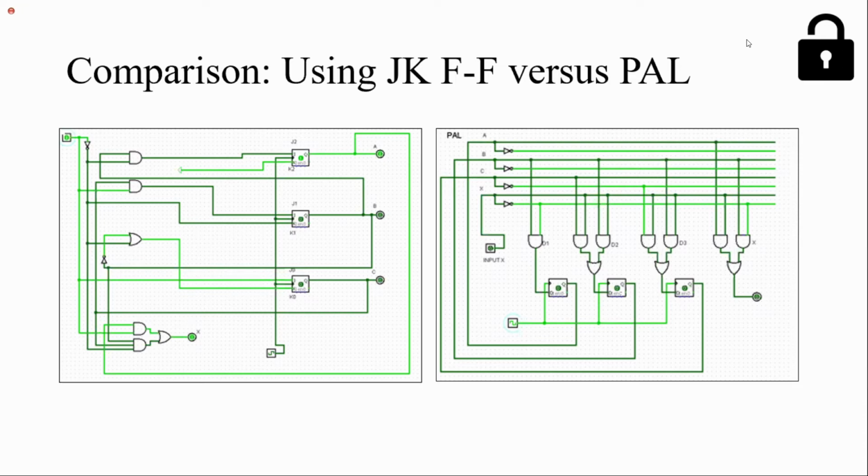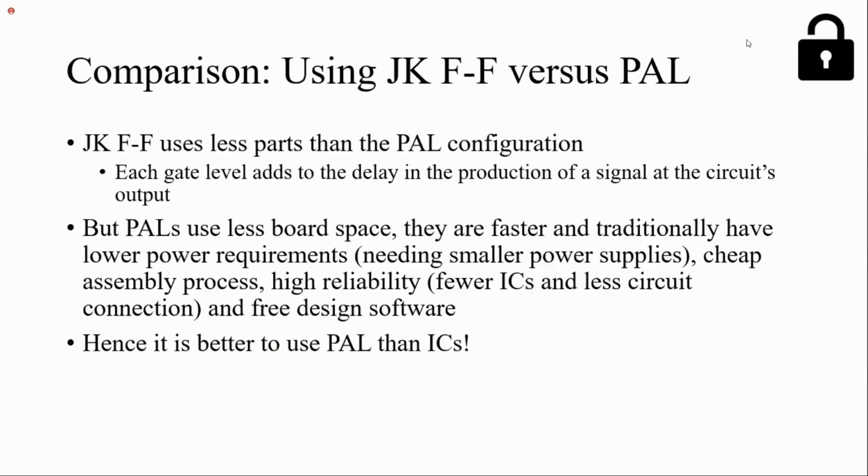Plus the fact that an FPGA is volatile and you have to keep it on, or maybe you have to have a ROM somewhere else to store the data so that you can run it on the FPGA any time required. That would be the other issue, right? Yeah. Okay, so if there's not any more questions, I'll move on.